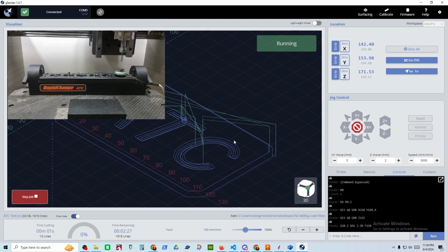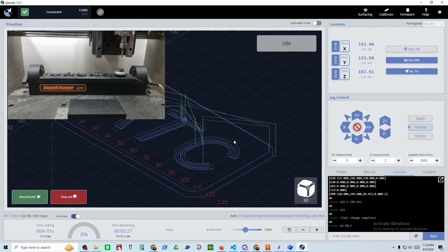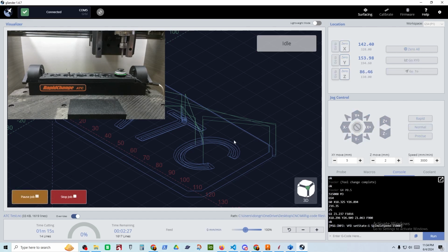Now it's setting the tool length offset, which is separate from the work coordinate system, which is very nice because each subsequent tool change will find its place in Z, and you don't have to set your Z work coordinate every time you start or change a tool.